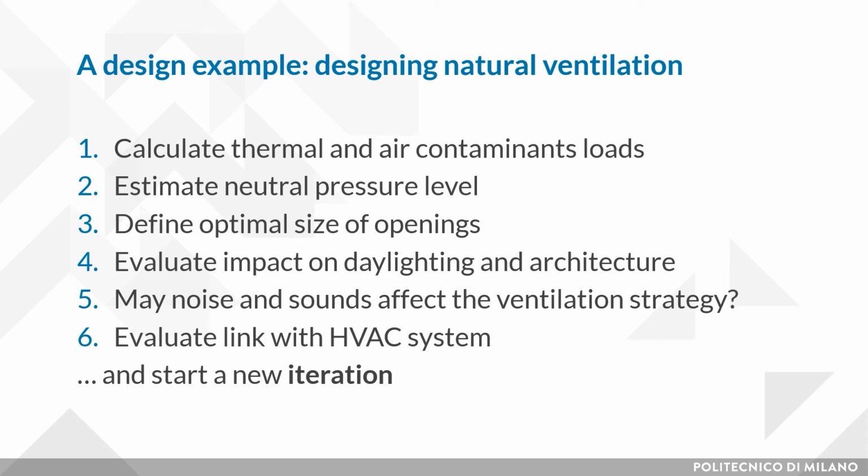If you think of natural ventilation, normally you would start from the loads that you have to satisfy in terms of thermal loads and air contaminants. You estimate the neutral pressure level, define the size of openings, evaluate the impact on daylighting and architecture of the size of these openings, and then you may want to consider sound and noise, and then the link with HVAC systems. And guess what? The best thing you can do at the end is to recheck all these things in an iterative process to make sure they all work well together.